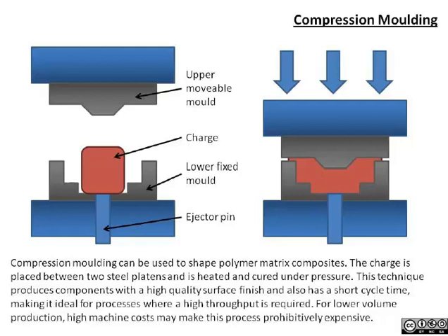If we partially cure, so that we have a little bit of what we'd call green strength of the material, or if we go with a long molecular weight polymer that has some properties, it's viscous and it is basically self-supporting, and then we want to cross-link it a bit more after the fact, we can use compression molding. So in this case, our workpiece is labeled in the red little square called a charge. So this would be what we call a green piece.